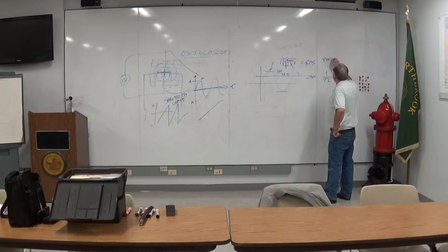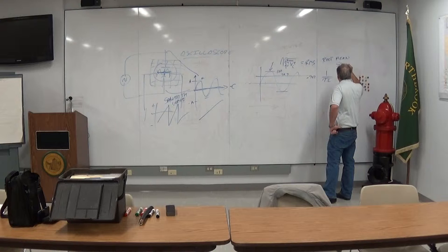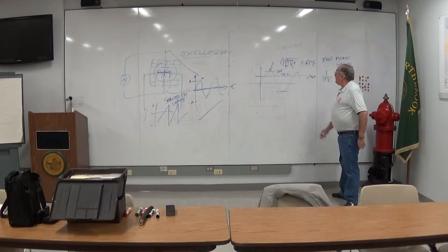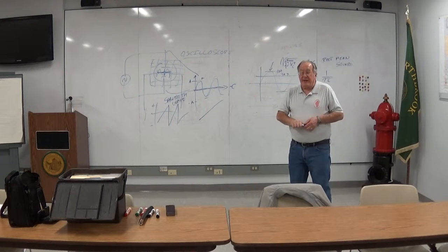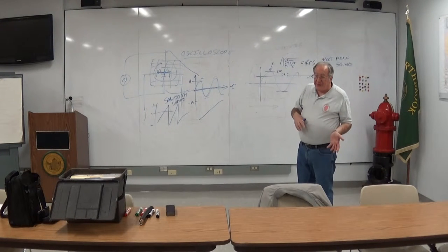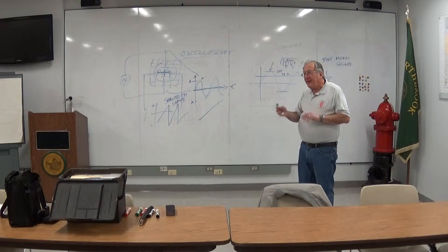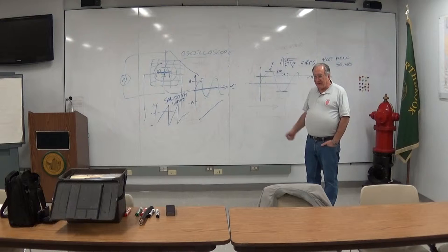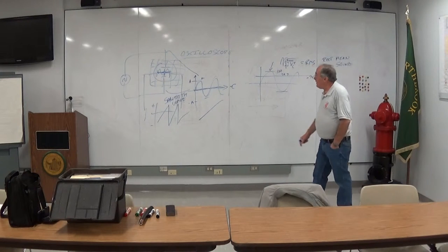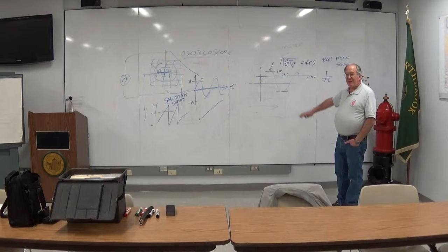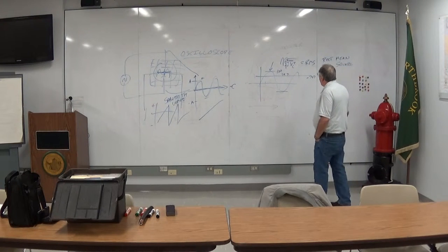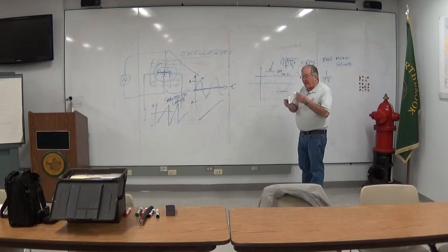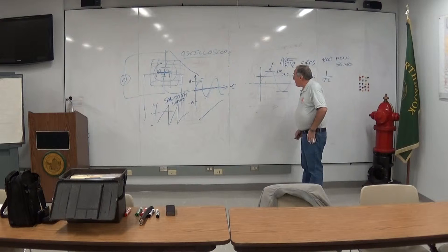or root mean square measurement of voltage. And by the way, if you look at an AC voltmeter, it'll say it's a true RMS voltmeter, meaning if the waveform is not a sine wave, it has internal circuitry that will figure out what the real addition of all the harmonic content is that will give you the DC equivalent. And if it's not a true RMS meter, you might not get that value if you are not looking at a sine wave, but you'll get something close.